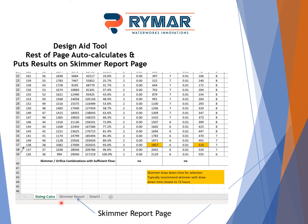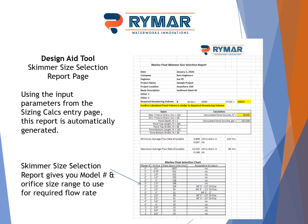At the bottom of the page, there's a skimmer report page tab. Simply click on this tab and it will take you to, based upon your engineering judgment based on your soil type, you would select one of these skimmers to specify. You'll notice that in many cases you'll have multiple choices and you need to look at the orifice configurations. For example, the 3-inch skimmer with a 2.5-inch orifice will drain the pond in 94 hours, which is actually slower